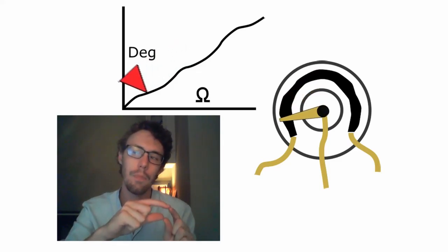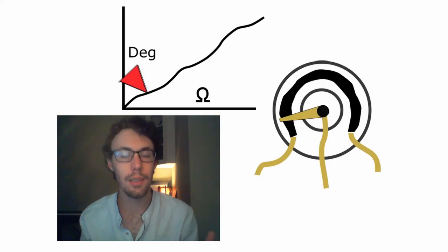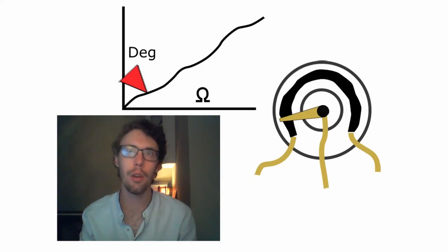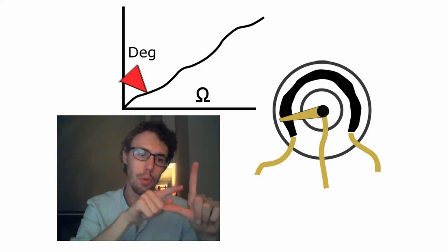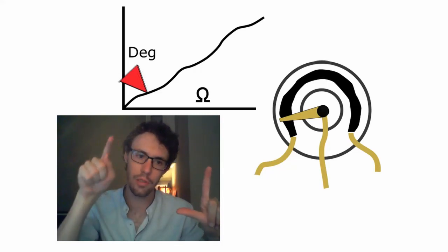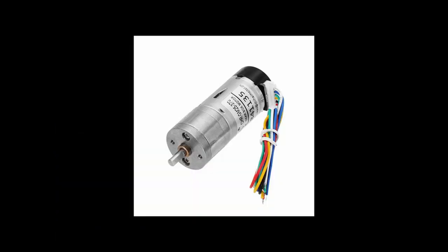So that means you can mitigate this in your programming code by not just assuming it's linear, but taking sample points and then sort of mapping out the resistance to the correct position, and then you get a more accurate result. But it doesn't matter. We have a much better way of doing that if you're going to use digital systems, which is the encoder.